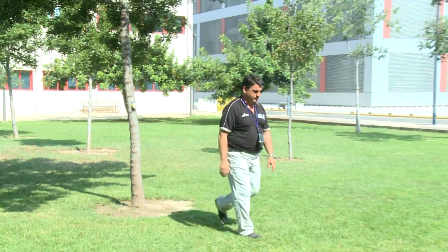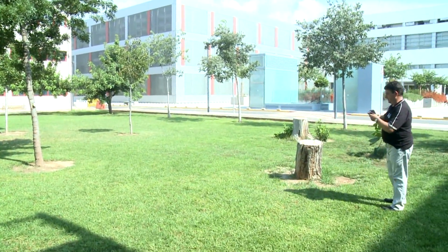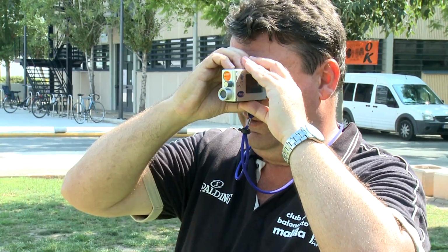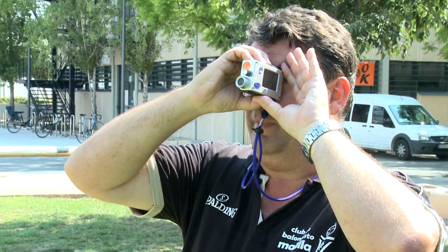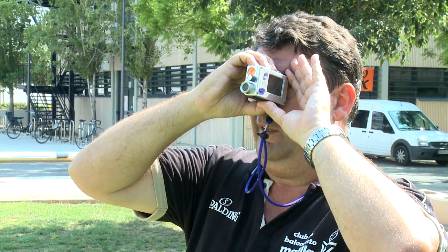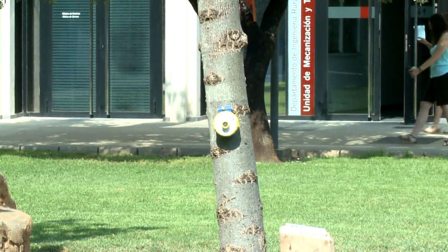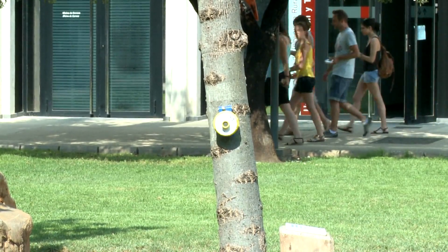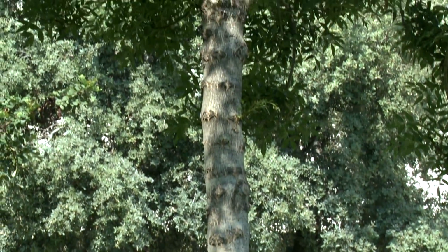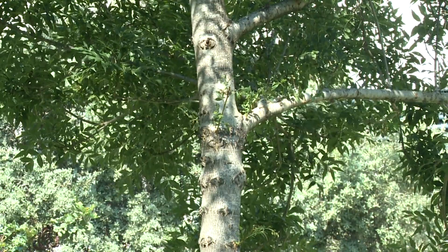The observer will walk until a distance similar to the height, and then from this point will connect first with a view to the transponder, and then will view and record the height of the tree. To measure the height of the tree to the base of the living crown, we perform it the same way. Place the transponder at the DBH section, and finally view and record a point of the tree trunk placed at the insertion of the first living branch.